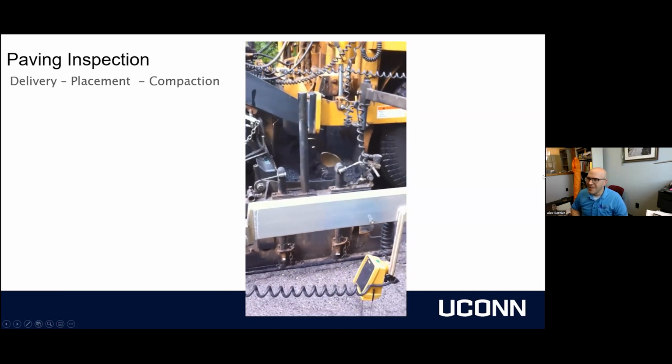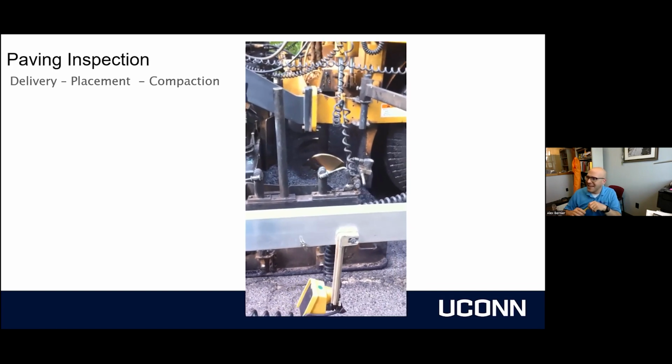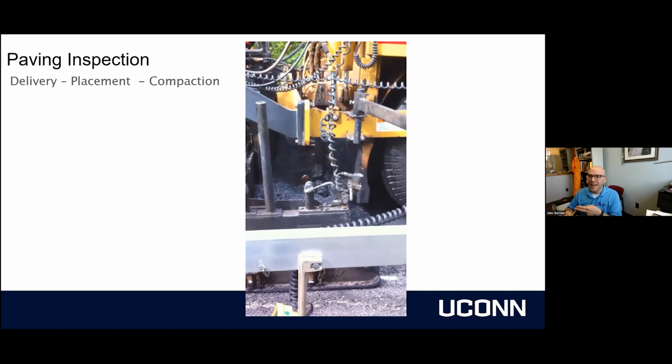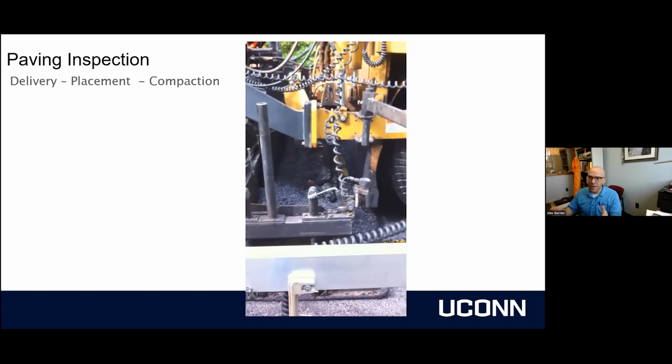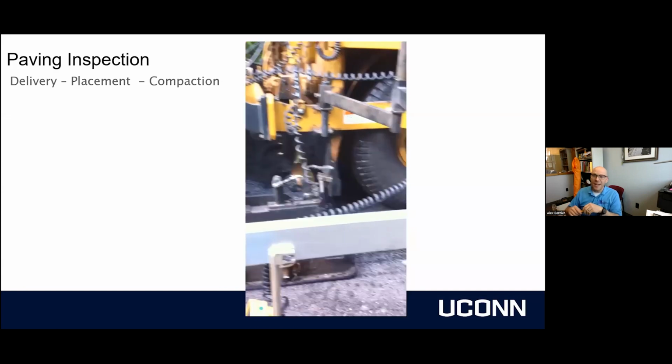You don't need to hear that noise. Imagine loud engine noise all day long. That's what paving is on site. But the idea here is the paver, the slat conveyors, and the auger should all just be going a constant, slow churning speed. If I'm ever acting as an inspector, and I'm on site, when I see people running around, that's a bad sign. It doesn't mean they're working hard. It means they weren't prepared. I honestly like to see people leaning on their tools because it means everything is working right.